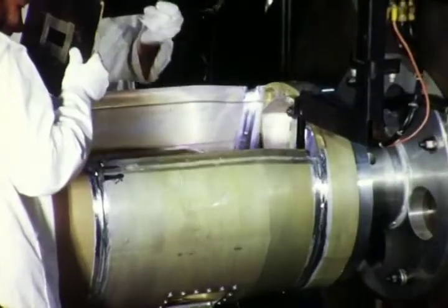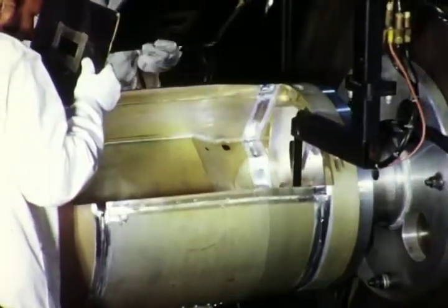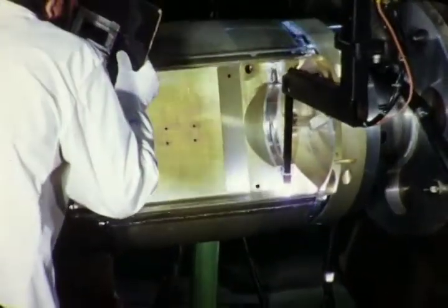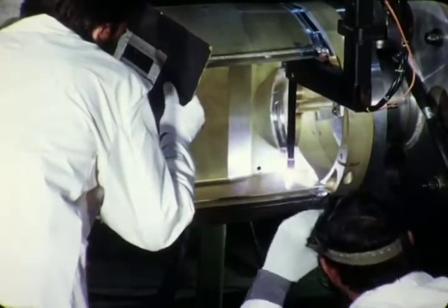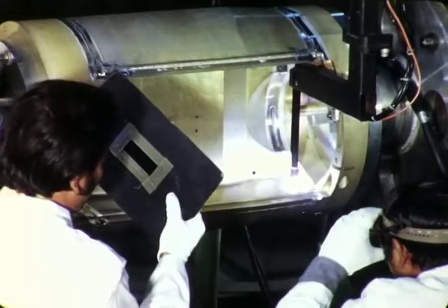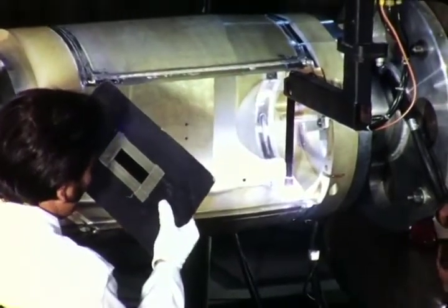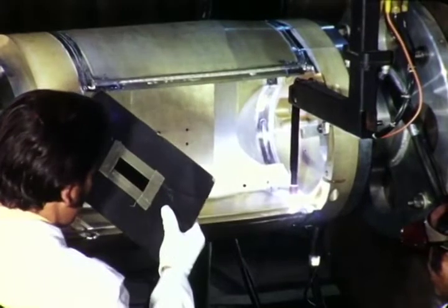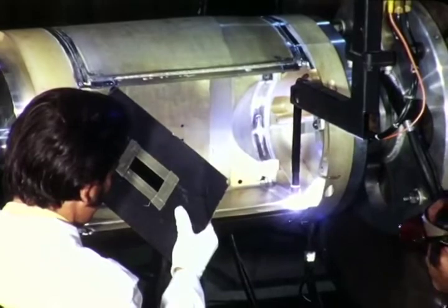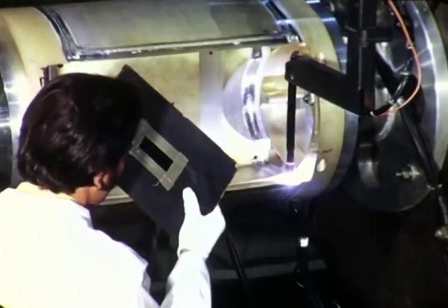The weld configuration at this end, the aft end of the nacelle section, is considerably more complex, having 5 radii in the cavity, none of which center on the turntable axis. The only data needed to program these arcs were the polar coordinates of their centers. Using these coordinates, the computer calculates the necessary relationship between the two motions on a continuous, real-time basis and provides the proper commands to maintain it throughout the arc. The main command data and the position feedbacks of the RAM and turntable are continuously displayed throughout the welding cycle.